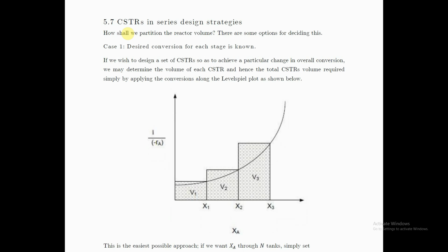But we also said that's also giving us the worst use of the volume. We are seeing now that as we partition the one big CSTR into multiple CSTRs, we are also getting closer to the ideal behavior. So PFRs and batch reactors, those all have disadvantages, right? But with the CSTR and its advantage of simplicity, we are still able to start to get better operation.